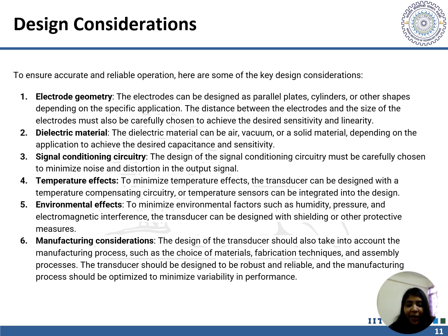To minimize the temperature effect, the transducers can be designed with temperature compensating circuitry, or basically using temperature sensors which can be integrated into the design. Next point is the environmental effects. To minimize the environmental factors such as humidity, pressure, and electromagnetic interference, the transducers can be designed with shielding or other protective measures.